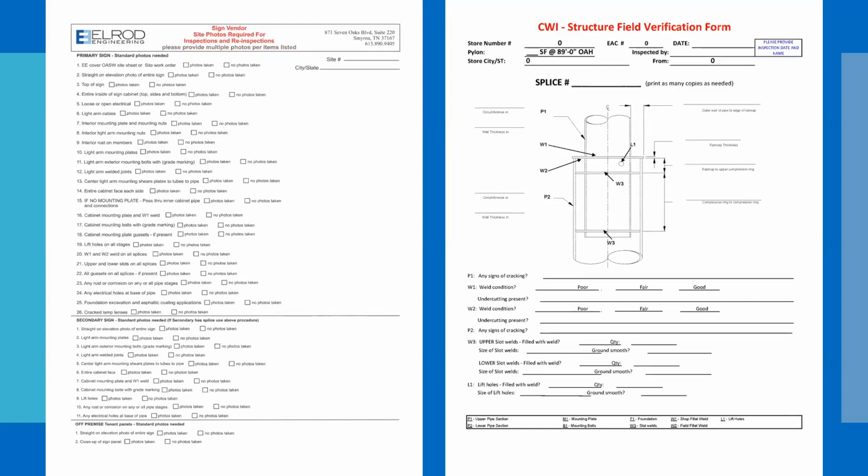A lot of the ones we do for one of our clients are signs that we designed, but what's designed isn't necessarily what goes into the field. There may be variations on wall thicknesses or heights, information like that. So we always want to gather accurate in the field information, even if we designed the sign several years ago, just to make sure that our analysis is accurate.